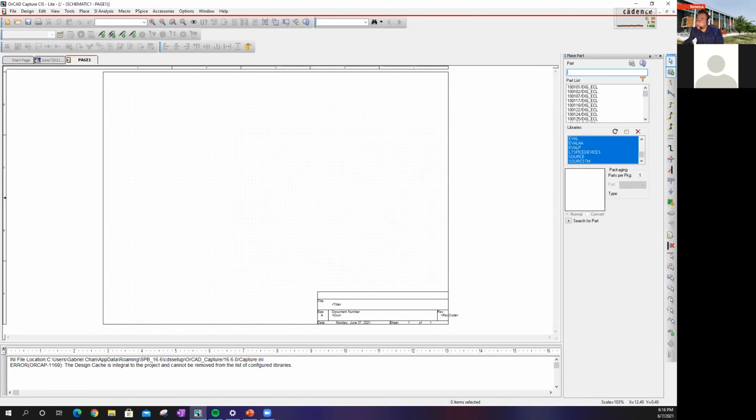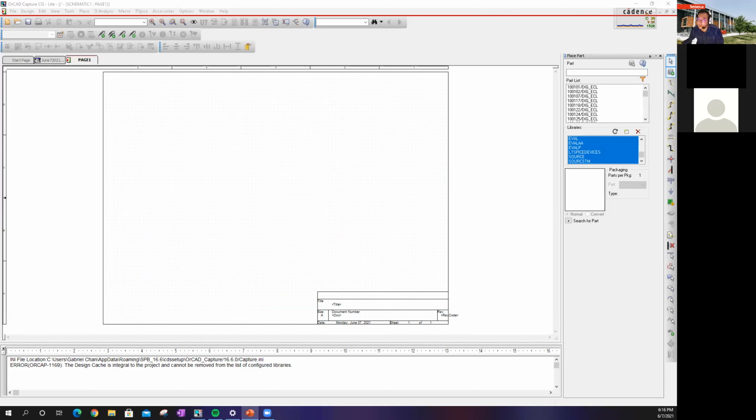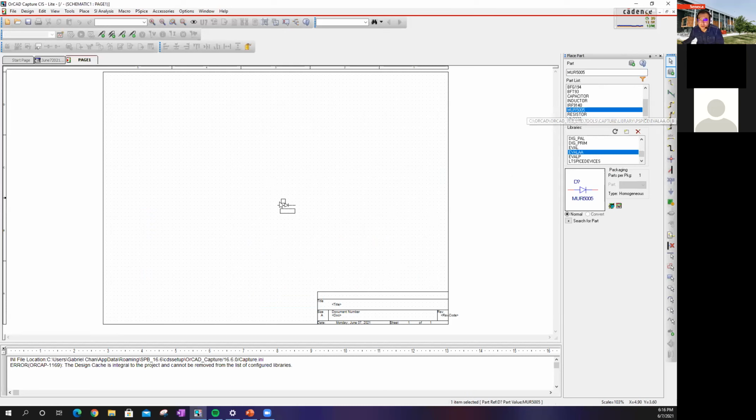Let's say we want to create the NPN transistor as a switch logic, which is this picture right here, which I will recreate for you guys, so don't worry too much about that. The first thing we need to do is add some resistors. When you click on resistors, it's usually in the eval A, and you'll see big letters, resistor. Then you can put your resistors in. Oh, that's not resistor. To get out of it, you just click escape.